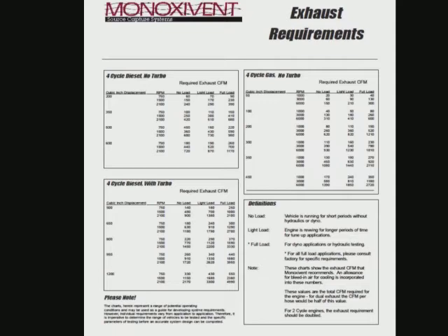And we always want to size our systems around the worst case scenarios, right? So if 90% of the time you're only running at idle, but 10% of the time you're running at high rev, well, that's how we have to size the equipment to make sure that we're set to handle worst case scenarios. One note on this sheet, 2-cycle engine, you double that because it fires twice as many times as a 4-cycle engine. So just to give you a little heads up on that.